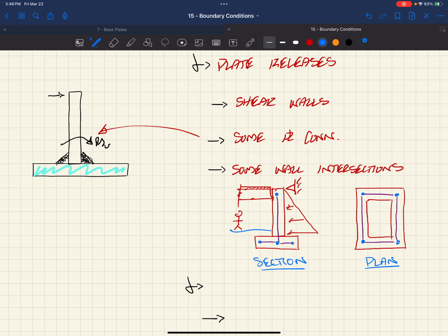One other thing that sometimes comes into play is, you have a slab on grade usually in basements as well, right? And a slab on grade can sometimes, if you want to justify it, you can assume that slab on grade restrains the base of that wall from sliding. And maybe that acts as the restraint to help create that pin. Another thing to think about relative to walls and intersections.